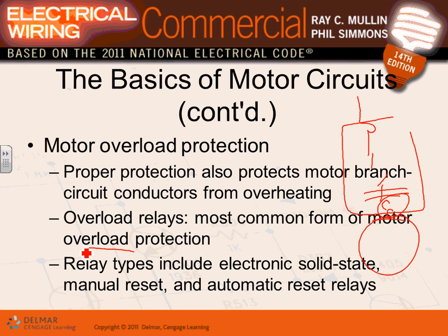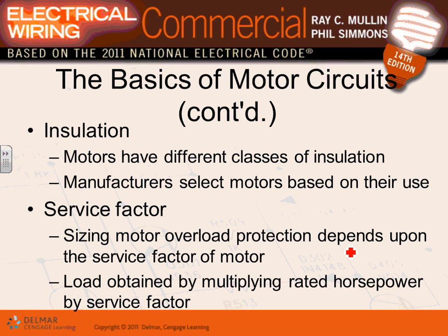Relays are the most common ones, guys. They have electronic solid state relays, or they have heaters, and they are set manually or automatically. You can set it to manual or automatic. So when it comes to overload protection, you have two options. I'll show you in a second. You have electronic overload protection, which is the most common now, or you have the thermal overload protection.